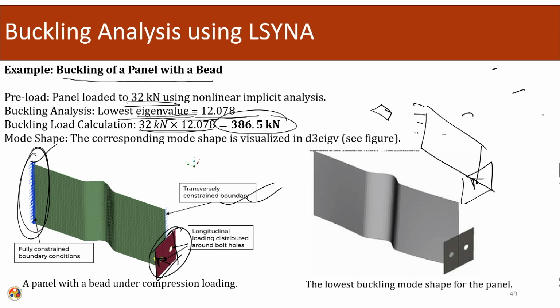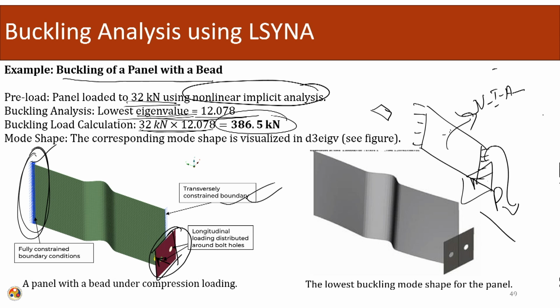We preload the system and analyze it using nonlinear implicit analysis, and the results we get, we will use as an initial condition for my buckling analysis.